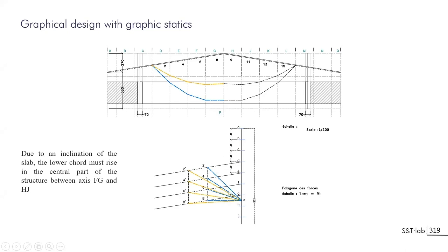So if you know this line and you know that this has to be horizontal, you can draw from the middle of the load line a horizontal line that gives you this point. From this, you will be drawing this line corresponding to each of the vertical struts. And from the intersections, we'll get all these rays of the funicular line, and you can draw it on the figure.